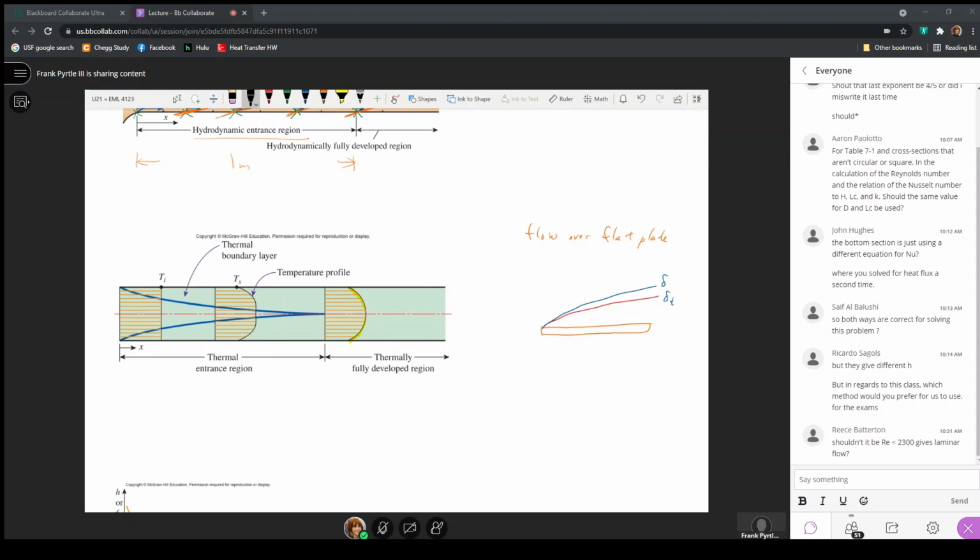Well, I know that at this surface, where the fluid is in contact with the inside of that pipe, the heat transfer into the fluid can be written, or the heat flux, let's say at the surface, is equal to minus k dT/dr at r equal to capital R, where R is the inner radius of the pipe.